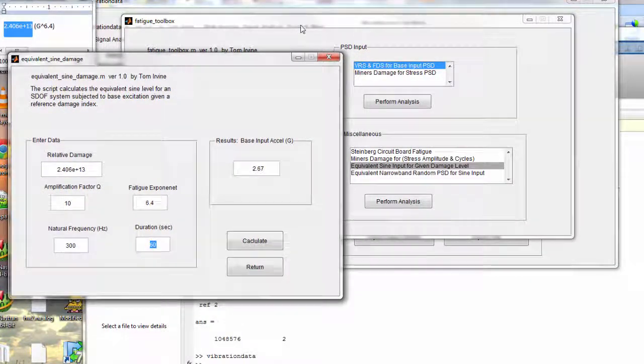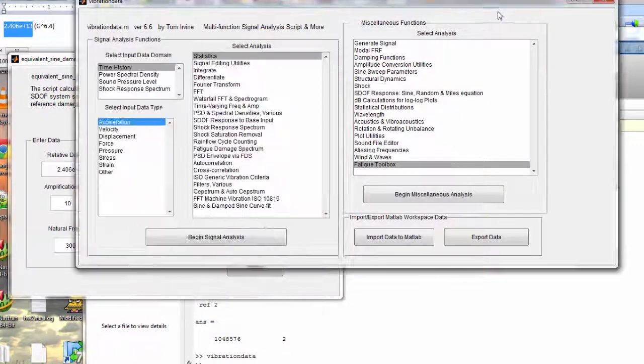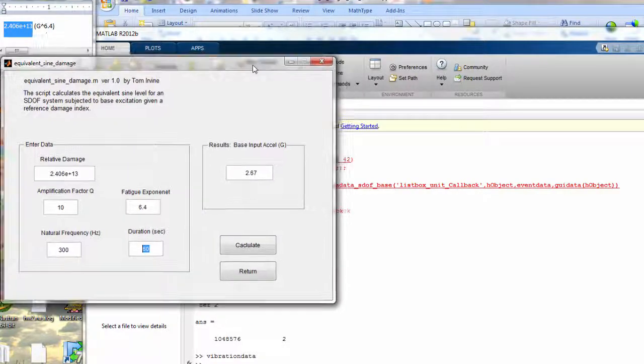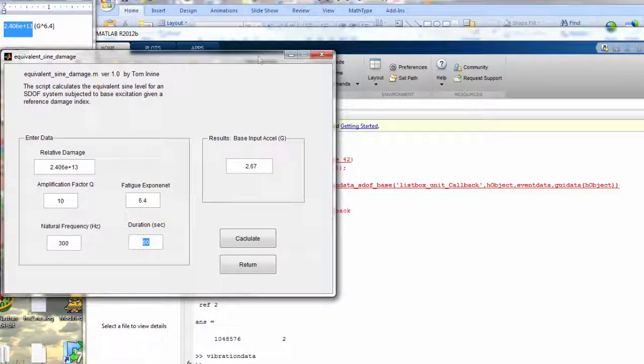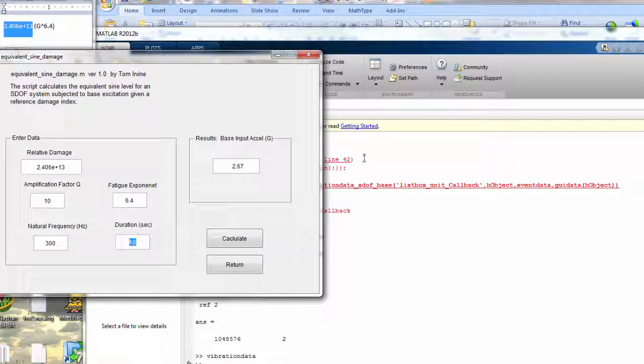Another thing, and I do need to be honest and upfront with you here, is that we do the best we can. We're engineers, we're not physicists. And I've been in meetings with some of my esteemed colleagues who say, and understandably so, that anytime we're doing our analyses, especially like a finite element analysis or whatever, these Q values or the equivalent damping, that's the biggest uncertainty factor. And to some extent, I agree with them because damping can only be measured.